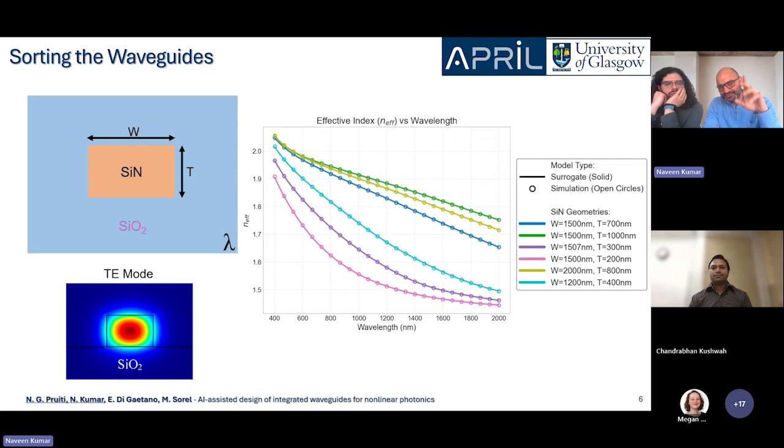Okay, so this was just one of the waveguides. And now think that if we have that simple waveguide and we have 2, 3, 4 geometries, those are the meta waveguides. We have done that as well, but for those we are getting around 2% error. And that can be solved if we make the neural network more complex. But remember, these are done for single mode, not multi-modes. For multi-modes, we have to use, let's say, regression-based models later on as well, because we don't know what type, or we can manually input and change the neurons per hidden layer and then get the output, or we can do a regression to get the error at the end at a lower value.